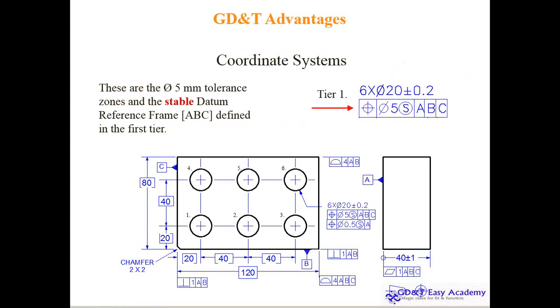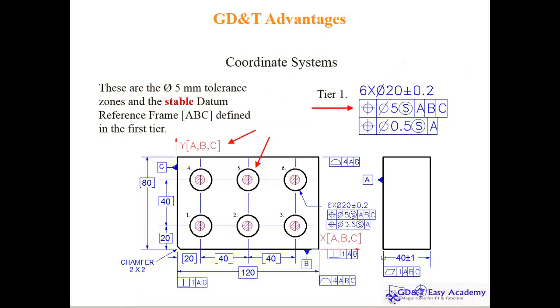The coordinate system is also a primary part inside your system. If you have a primary coordinate system, every independent feature is referenced because of this, giving tolerance with respect to the primary datum. This is across axis to axis. These are independent holes. This independent hole can vary, and this is a tighter tolerance from axis to axis, because this is critical: across the counterbore we are going to assemble your pins, but alignment is critical for us. If in your case alignment is not critical, you can keep it tighter here and looser here, that depends.